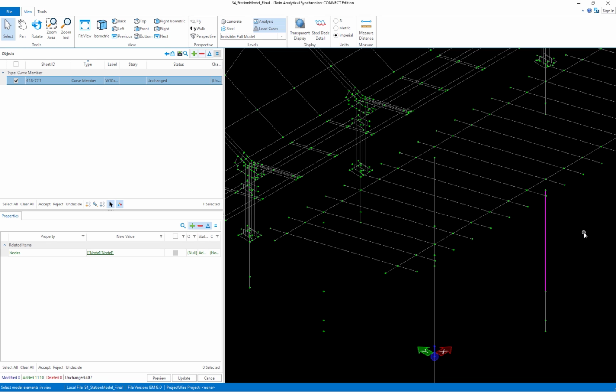Or lastly, I can work with my architect and ask them to adjust some of their placement points to ensure that those analytical members are intersecting each other. Now, since it's just the columns, I'm not seeing any other glaring information of where I might need to make those changes. I'm going to go ahead and leave it as is and attempt to make those adjustments once I get this model into my structural application.